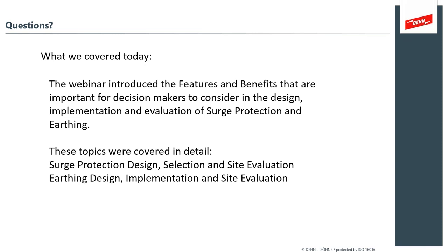However, if it is a client with sensitive equipment, or a client that has experienced some losses, or a client that is geographically on a hill or in a high risk area, an area with a high ground flash density, I would say recommending SPDs for that type of client would be an important thing to do.